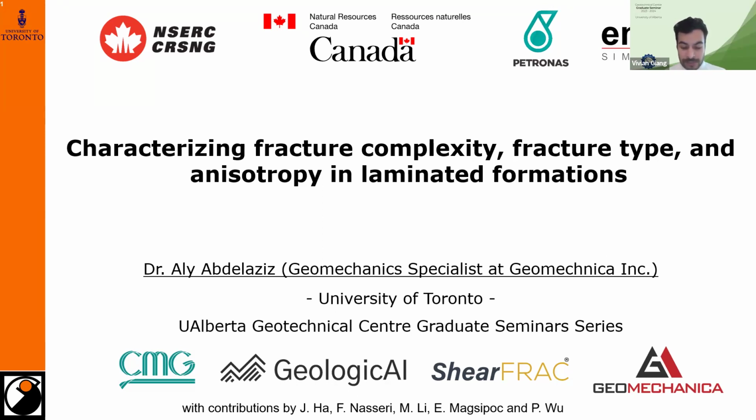The outcome of this experimental work is a new conceptual model that is not tied only to the magnitude of the in-situ stresses, but rather identifies the plane with minimal mechanical resistance, defined by the magnitude of the principal stress and the anisotropy in the tensile strength of the rock material.